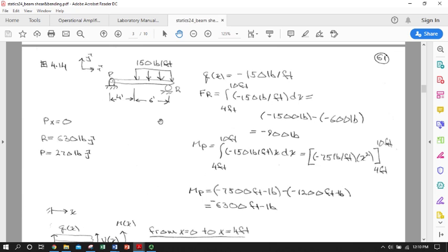So as usual, our first step here is going to be to find the reaction forces at the supports. And once we have those, we're going to start over here at the left-hand side. We're going to use our left-handmost support reaction to create an x equals 0 condition for shear, and then we're going to integrate forward along this open section, and we're going to see what happens with the loads that are applied by the cut off right-hand side of the beam. See how those applied internal forces change as we move from x equals 0 to x equals 4.